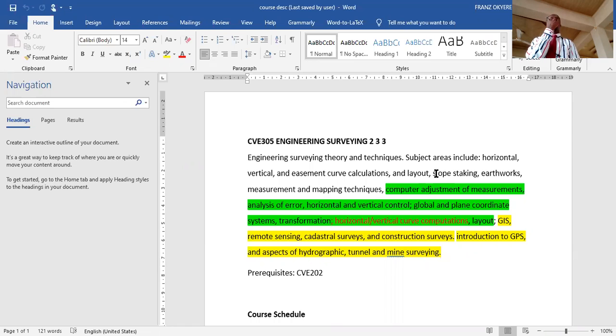Why is cutting important at all? As engineers, why is cutting and filling a place so important to us? Open your mouth so that online can hear you. To make places level. What really? Any more? To get a gentle slope. Okay. So I think to grade to a particular slope. Let's assume that we really want to have a particular slope. Then we need to decide that we need to cut so much, isn't it? Or to fill so much.